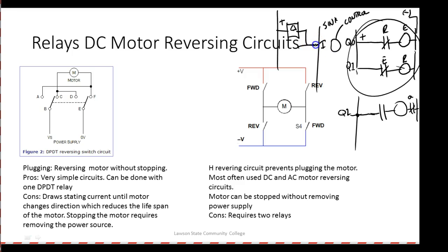So our PLC is set up for sinking inputs, which means its inputs are referenced to the minus. So it means all my sensors are going to have to be referenced to the positive, right? So a sinking PLC input requires a sourcing input device. And this is pretty standard in the US, guys, if you're not using AC.